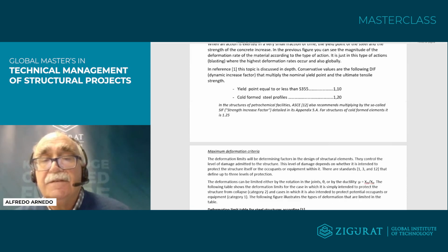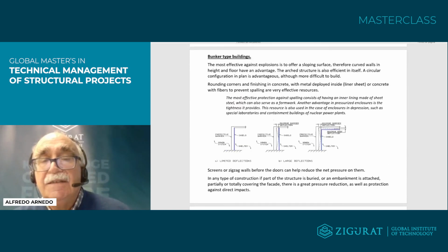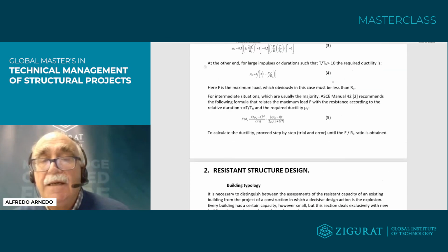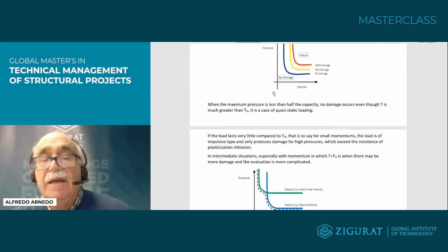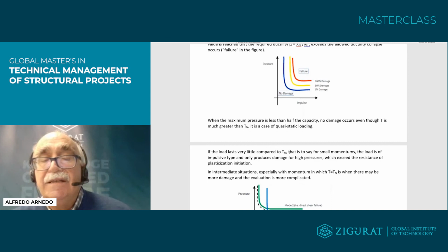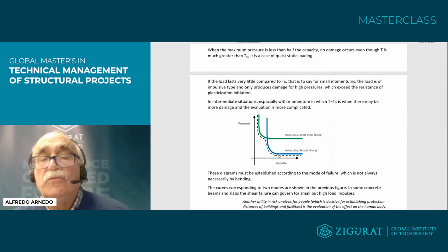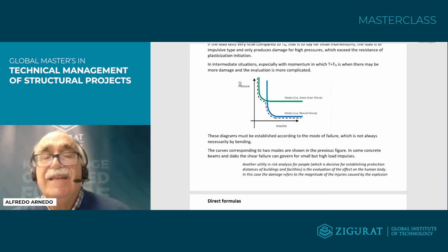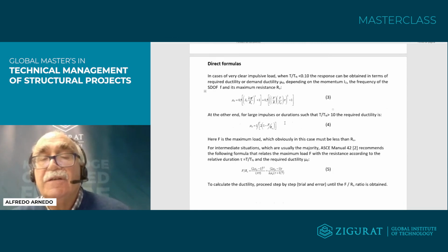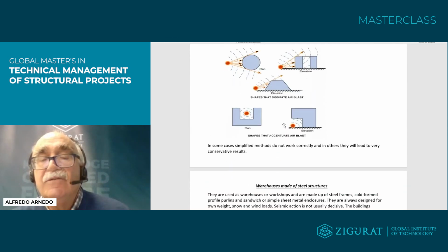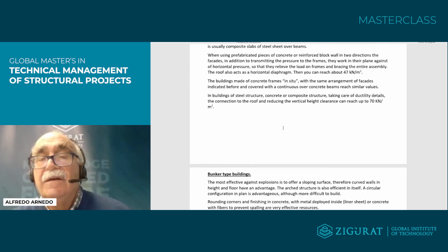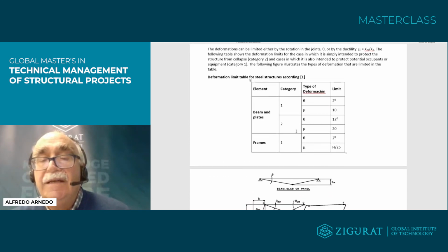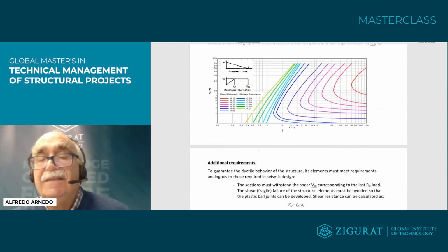Here is to find which is the weak point, and to make a correction of this. So when we cope with the main structure, and we consider the possibility in secondary structure, and we accept sometimes different limits of allowable ductility, then we can accept the design.